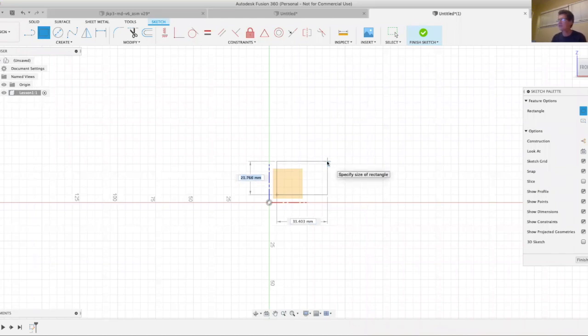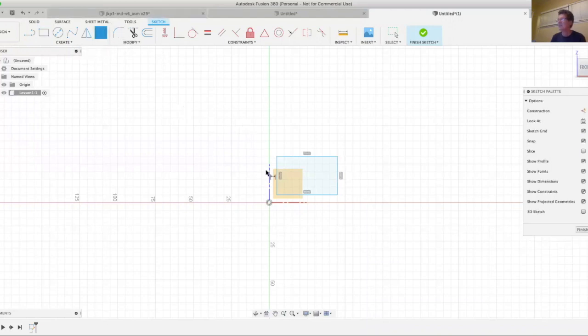You see the dimensions? I can either just arbitrarily let it go like I would with CorelDRAW or something, or I can actually specify, or I can rely on the snaps. So right now, I'm going to go with these dimensions. But if I want these dimensions to be easily edited, I can always add specific dimensions.